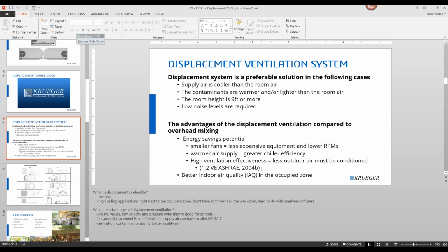But we don't provide any special options for providing the units with a built-in fire damper or really any damper mechanism. Since they're so low flow, a lot of times any adjustments can be made just directly in the ductwork with any kind of damper device. So we'll provide them with a measuring station that has a butterfly damper if they want, but that's really the only damper option that we provide.